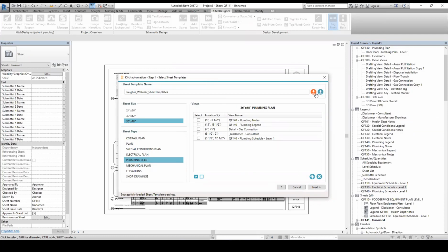And so this is something that you can do if you need to, but at the same time, when you press save in Revit, it saves all these sheet templates to your Revit file. So if you're doing this in your template, you just need to save your template after you do it. And then anybody who opens the template file, regardless of where they're at, will already have all this stuff set in here. And that's the same thing for all of our settings. When you save Revit, all of our settings basically get burned into the Revit file so that they stick with it, regardless if somebody else doesn't have those things.